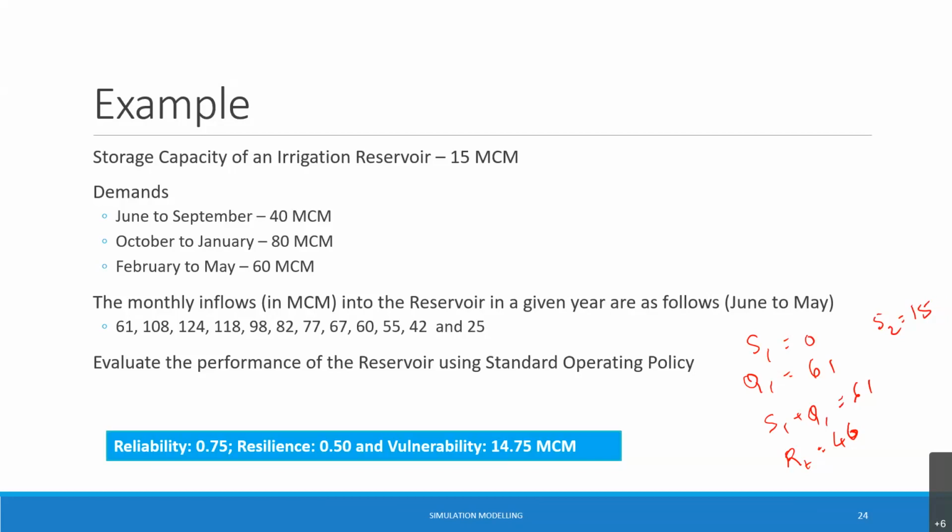Now, if I look at this problem, as irrigation, for example, I'm interested to know whether this is satisfactory or not. Maybe in terms of reliability, it's okay because most irrigation systems are usually designed for a 75% dependable flow. You only give an assurance that 75% of the time you will be able to meet irrigation demand. So 25% of the time you will not be able to meet it. So from the reliability point of view, maybe yes, it's fine. This result is fine for me.